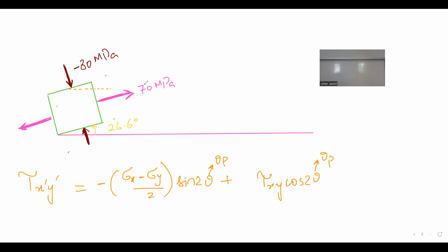So stress y equal to 0, tau xy equal to 0, because you can imagine if I'm putting a load like this and I'm actually taking a cube of this shape as well, then the shear stress is also 0 technically. So technically, 2 megapascal applying like this has what principal stress? Stress 1 equal to stress x, 2 megapascal, stress 2 equal to 0, and tau xy equal to 0.